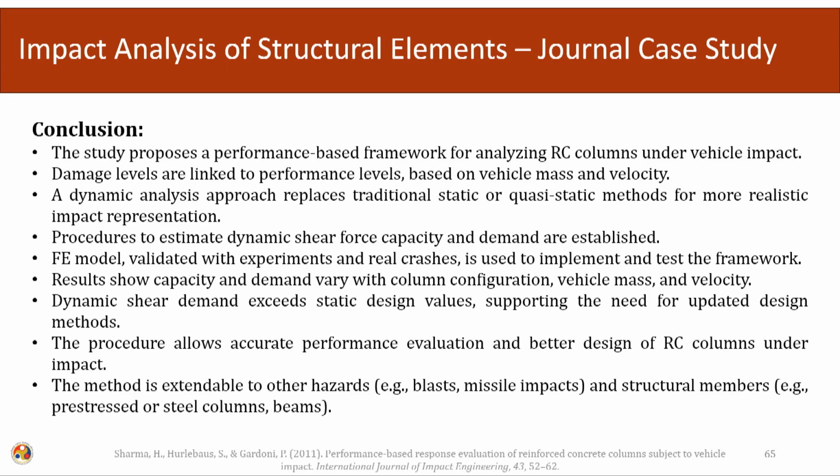So, what we were able to do in this study is propose a performance based framework for analyzing the RC columns under vehicle impact. We identified the damage level and linked it to the performance levels. We used a dynamic analysis approach, because in the dynamic approach we were able to see the effect of the inertial terms, the damping terms, the stiffness terms, and the interaction between the forcing function and the system, which is not available in the static or the quasi-static methods.